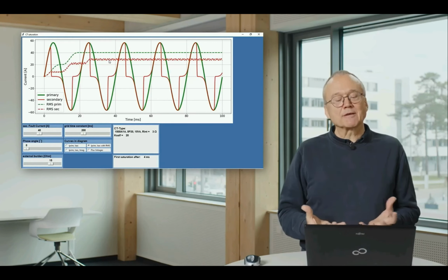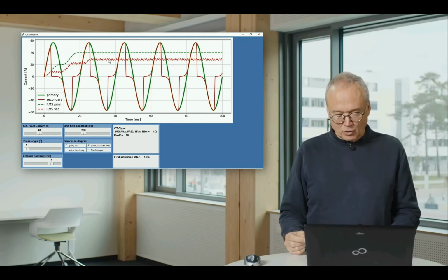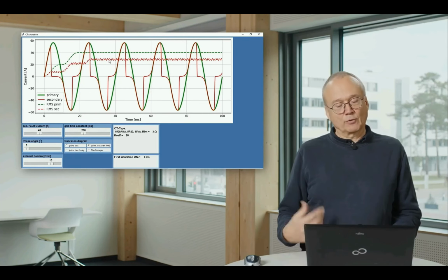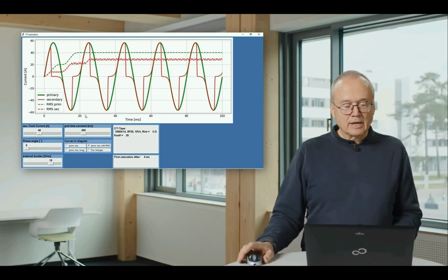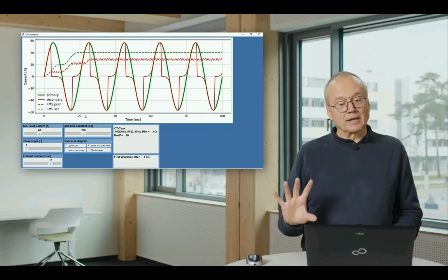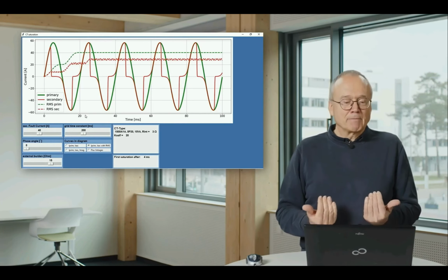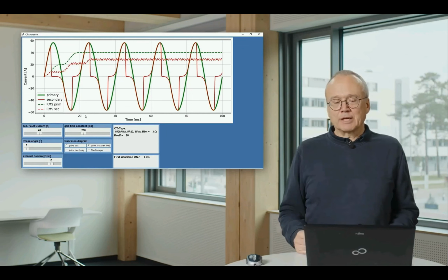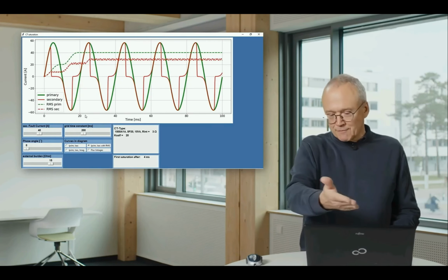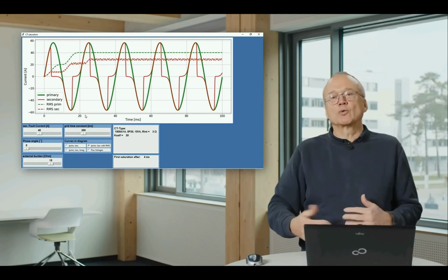And of course, we have to keep this effect in mind, as it can cause trouble. For that reason, it has to be considered and checked whether it causes trouble. You see, if there is a setting of maybe 20 amps, it doesn't disturb anything, because even what we measure here, the 30 amps, is still above the setting value.